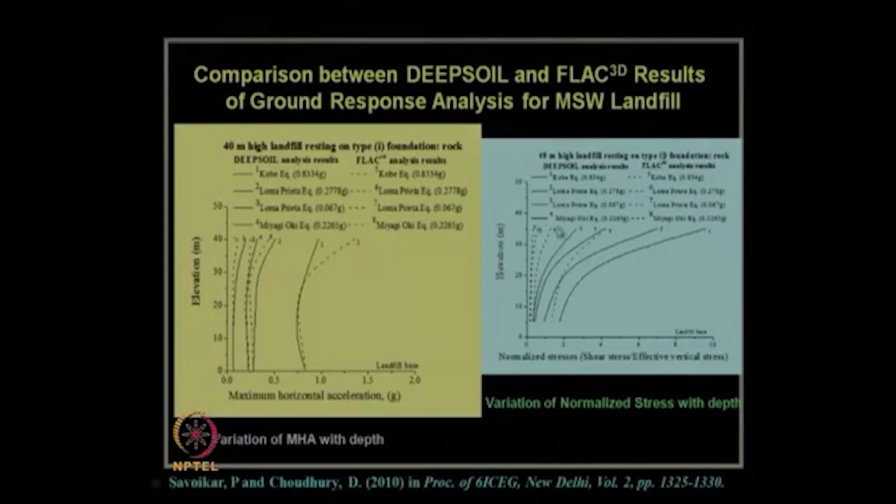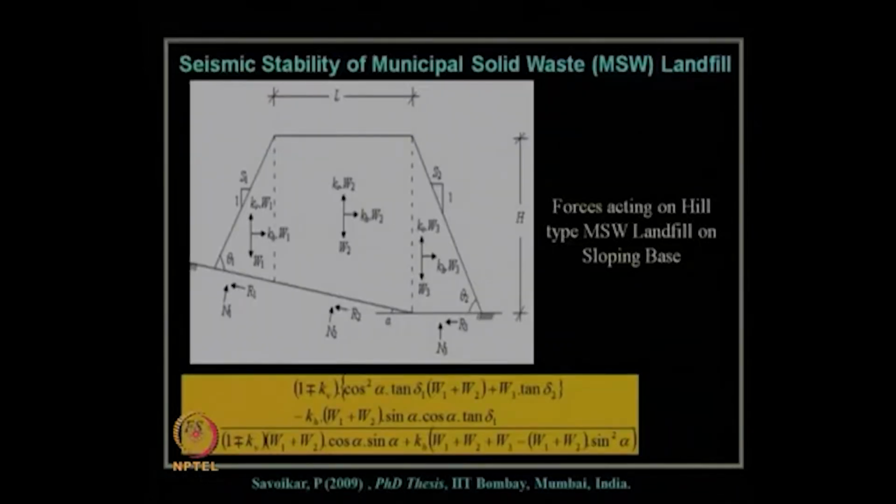Also, the normalized shear stress, how it varies with respect to depth as obtained in deep soil and FLAC 3D, is shown over here. The details about this work can be obtained in the publication Savaikar and Chaudhary 2010 in the proceedings of 6th International Conference of Environmental Geotechnics in New Delhi, volume number 2, and these are the page numbers. Now, once this dynamic characterization of municipal solid waste material is complete and ground response analysis is complete, the next step is how to design a safe, stable municipal solid waste landfill in the seismically active region.